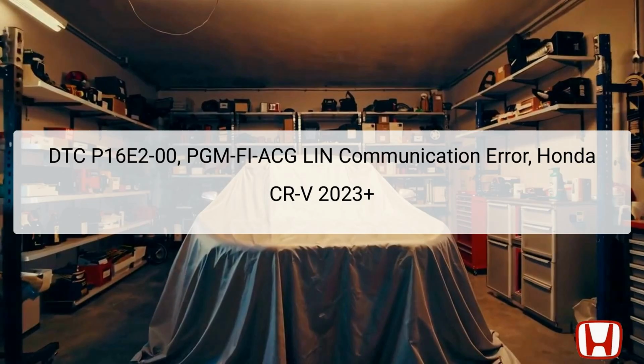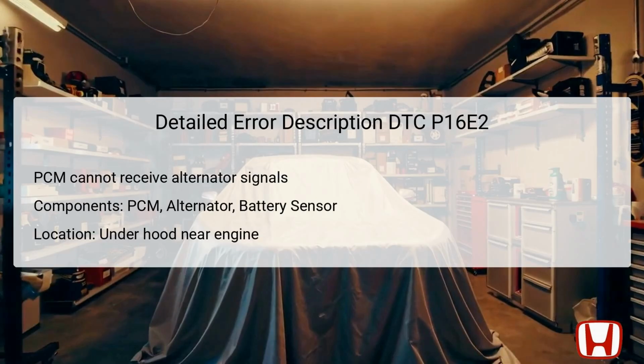investigation. This communication error may be manifested by a loose terminal at the alternator B terminal, which can prevent proper signaling between these components. DTC P16E2 indicates that the PCM is failing to receive proper signal inputs from the alternator, which plays a vital role in the vehicle's electrical system.